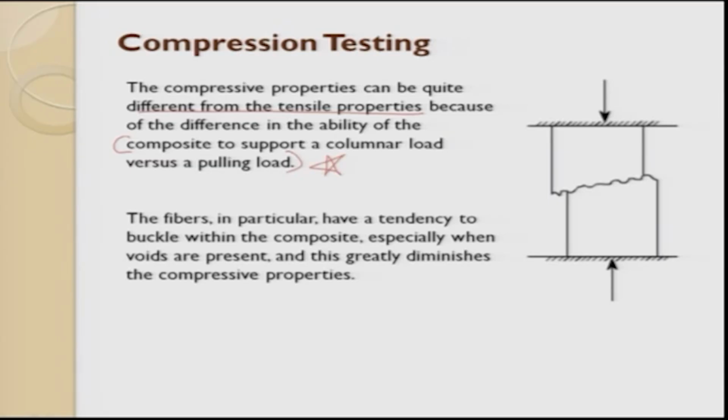In general, composites are very good for tensile load. For compressive load, the reinforcement doesn't take that major load. The fibers in particular have a tendency to buckle because you keep pressing. The matrix shears within the composite, especially when voids are present, and this greatly diminishes the composite property.